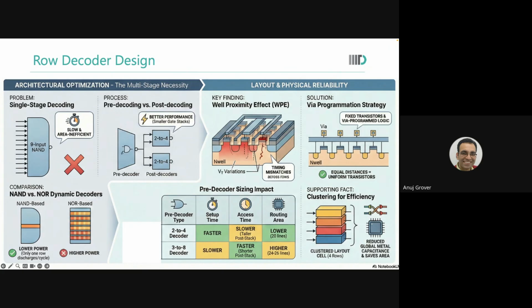So you say, okay, for 5 inputs, I will add the last 2 bits in the last stage. And the remaining 3 bits, I will AND or whatever in the previous stage. So you're doing it in stages so that your stack length is contained, it is limited, so that you get the right speed. Now, if you have used 3 MSBs in the first stage,